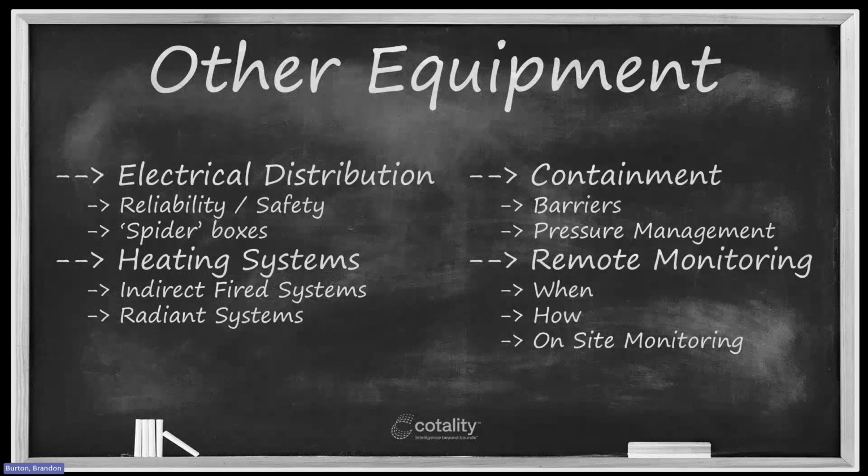Anytime that we're more than about 50% of that affected area being wet, being the wet area being more than 50% of the total area within the space, the value of containment starts to drop pretty quickly. So that's kind of a litmus test that I use. By using containment, am I reducing the amount of air that I'm managing by at least half or more? Then I tend to see that containment can be very cost effective.